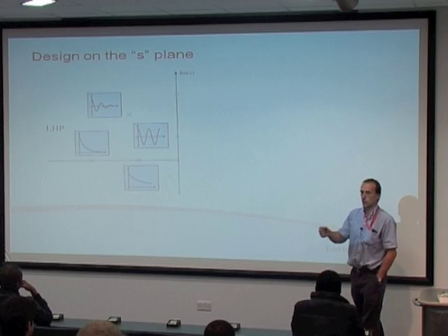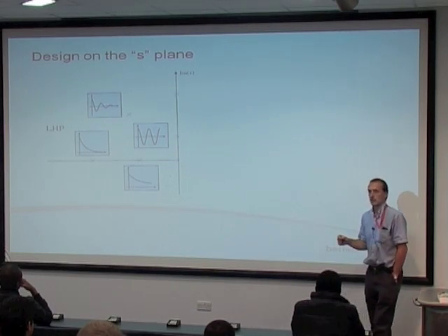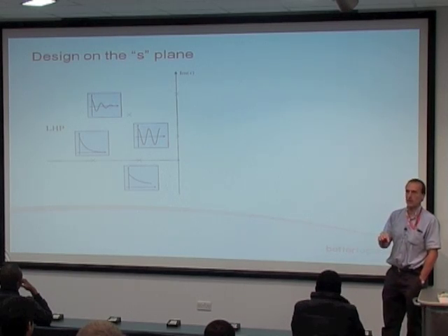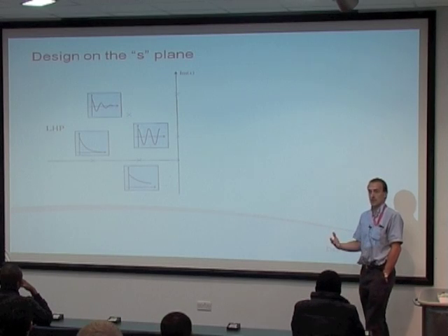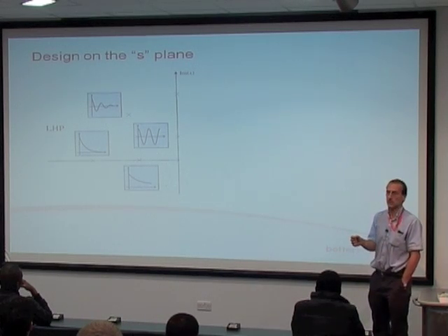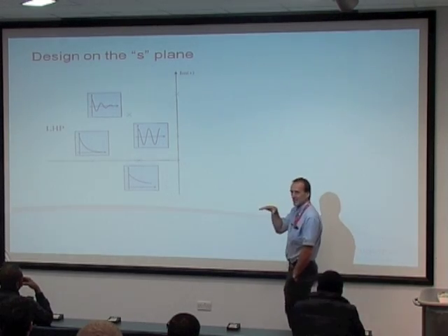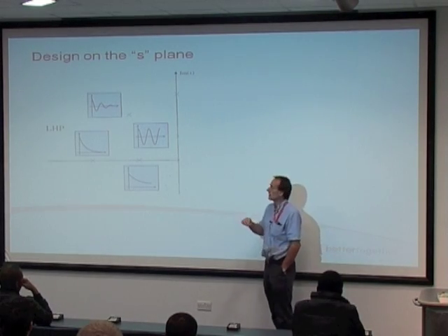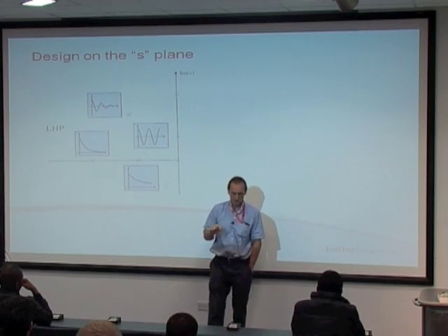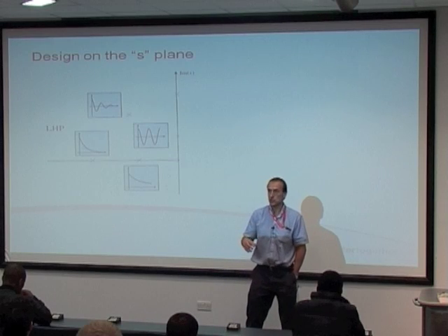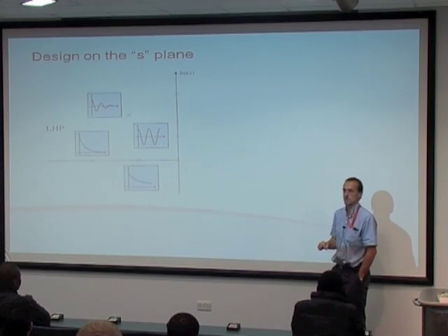In other words, the frequency at which it's really oscillating, which is different to omega n. The only time it oscillates at omega n is if there's no damping at all. As soon as we introduce damping, it sort of slows down a little bit. So the frequency or the number on that imaginary axis tells us about the actual frequency of oscillation of the physical system.